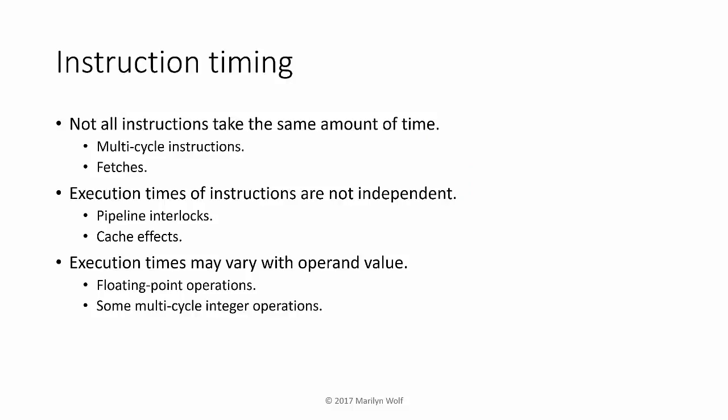We also need to understand how long each instruction for a given operation takes. In modern processors, different instructions can take different amounts of time. We may have multi-cycle instructions. For instance, in the ARM processor, we can perform an operation on several registers. Memory operations often require longer and may take varying amounts of time depending on the states of the memory system.